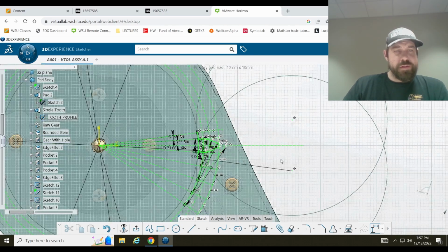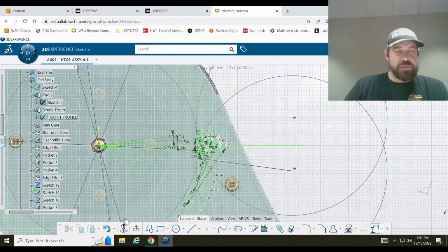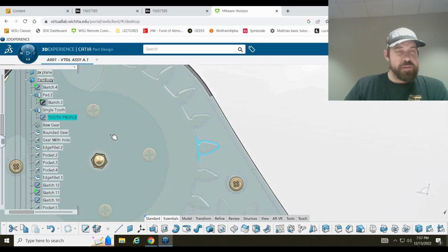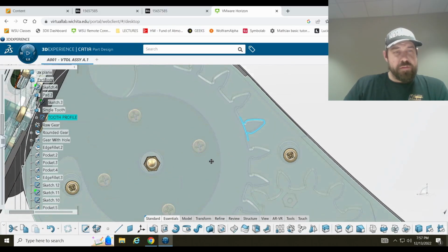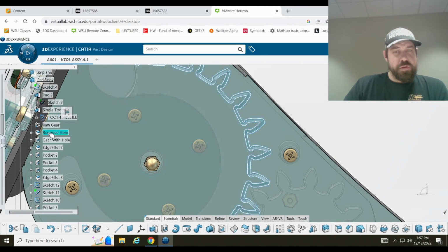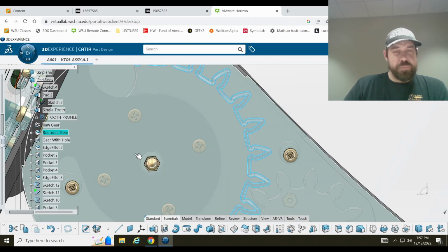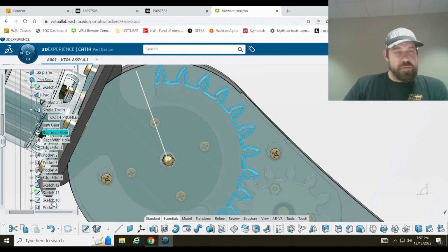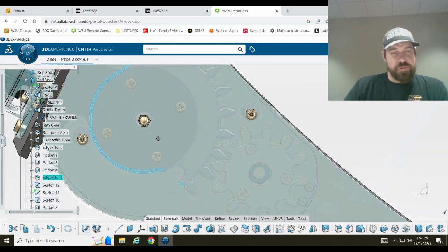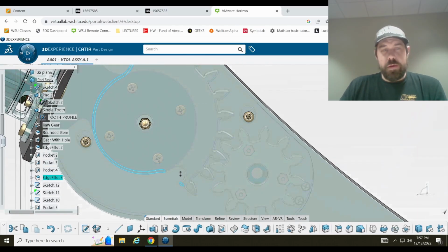So I generated an entire gear from that instead of just generating the 11 teeth. And then I modified that to have the hole in the center the size that I needed it, and the other pockets. And then in these other sketches, I'm making more delicate adjustments to the shape of this thing. So we'll look at some of these adjustments in the next section.